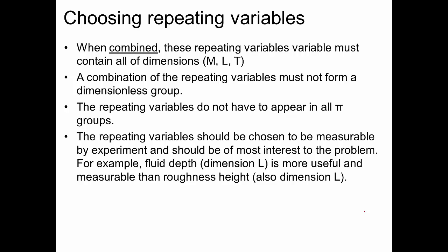So there's part of dimensional analysis where we have to choose some variables to fix. If we've got two dimensionless groups, we will have some variables that are going to appear in both groups. These are called repeating variables, and we'll have some other variables that appear once in each pi group. I'll go through an example on the board in a moment to make it fully clear. Okay, but that's choosing the repeating variables.